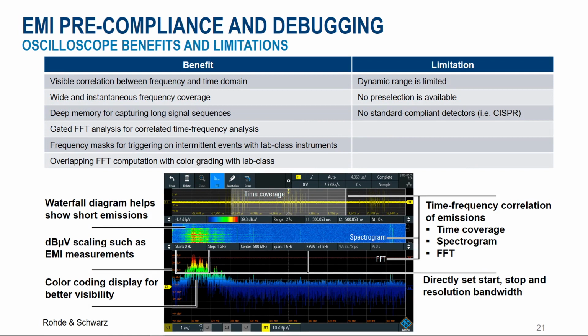An oscilloscope with a set of near-field probes is useful for locating EMC problems on circuit boards, integrated circuits, cables, and shielding, and it's an ideal tool for emission measurements from 30 megahertz to around 3 gigahertz. A primary benefit of a scope is it can transform signals from the time domain into the frequency domain using FFT.